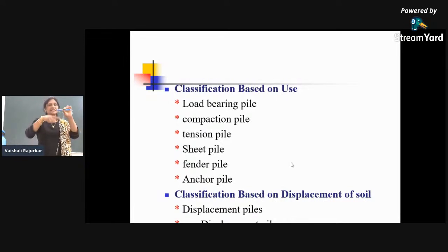So naturally it will disturb the surrounding wall surface. When we are inserting the nail into the wall, it will disturb the surrounding material of the wall, and therefore this is called a displacement material, which causes a displacement of the surrounding soil. Therefore, the same thing happens when we install the pile into the soil. If the soil is in a loose condition, due to the insertion of this pile, the surrounding material is getting densified.